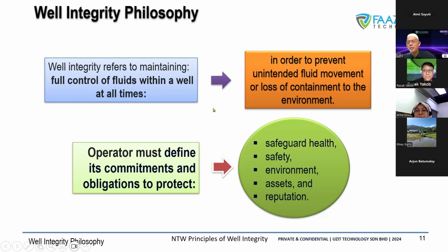Any failure, you must be able to record earlier. Some wells have sensors installed downhole, to be able to observe the pressure system coming from the bottom up to surface. At surface, there will be another sensor to check whether there is any fluctuation of pressure and temperature, or any difference in flow rate that can lead to a potential leak within the surface system.